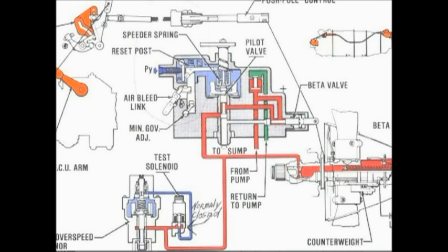The propeller is only going to operate between 1600 and it should be regulated at its maximum stop at 1900 RPM. Anything below 1600, basically the propeller is just going to be spinning out there in front of the airplane in low pitch position until you get above 1600, and then it'll start governing.